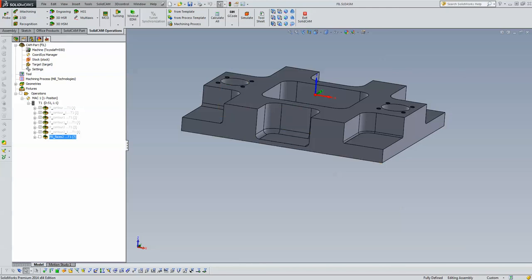I think one of them I answered before: what happens if the holes are perpendicular to the top face? What happens if the top face is on an angle, such as a 60-degree taper, for example, and will the top pick up the top hole over there as well? In that particular case, no. However, where it breaks through at the very bottom, if there's a regular hole that's flat on top, but it breaks through a surface at the bottom, it'll go to its deepest area in that particular hole.